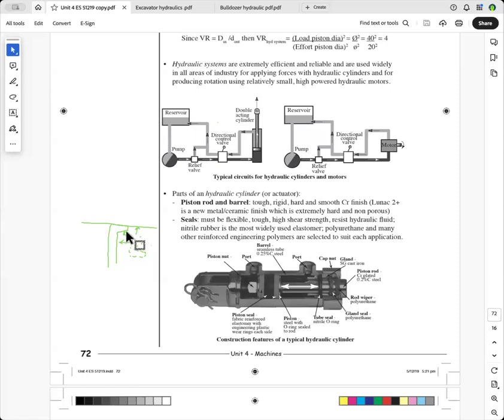And so this is tapered so that when the force pushes up against the angle of the seal, it's forcing the seal up against the wall, so the higher the pressure in here, the better the seal. And that's a sort of a self-energising effect to get the seals very good, and they won't leak.